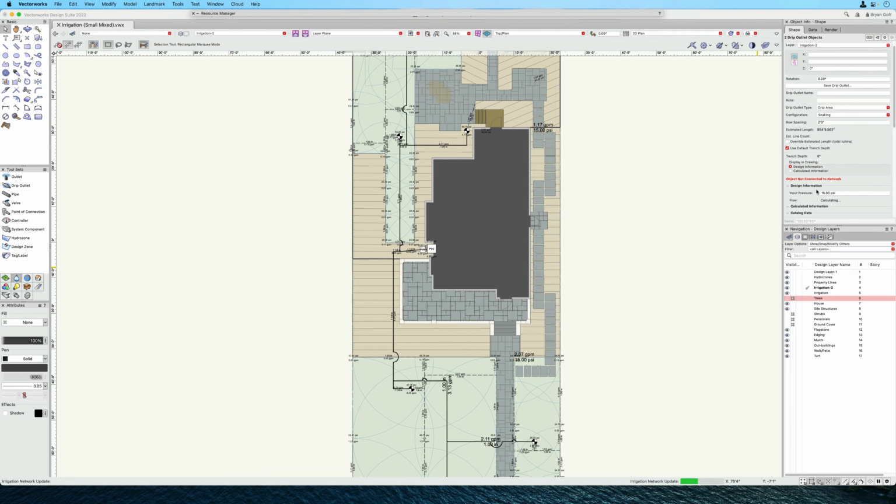If I go to snaking, that goes away. I have 854. What that's going to do is that is one continual pipe, just back and forth and back and forth and back and forth. It is not in a grid network. I wind up with 854 feet worth of friction. As we know, if you're used to doing this, I'm going to put water on the front side. It's going to work great. The end of that pipe, nothing's coming out. So we have a little bit of an issue. So you can choose what you want. Small little areas, you can go ahead and do snaking. Larger areas, you probably want to do branching.